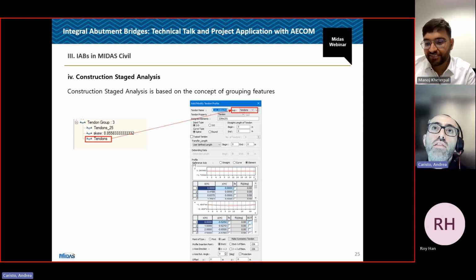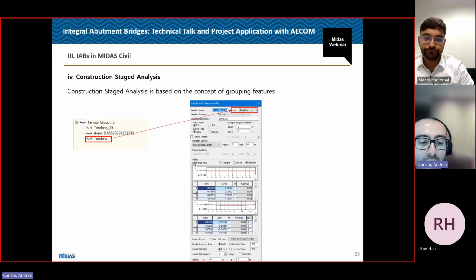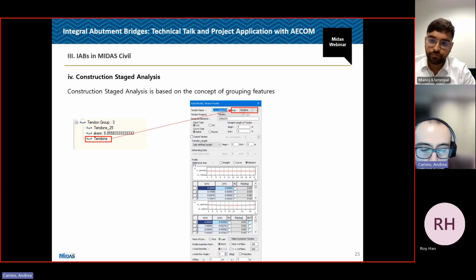So in this project, we have prefabricated beams, and we also have cast in situ deck with post-tension tendons. Now, the idea behind pre-stressed concrete, in very simplistic terms, is this: we all know that concrete is really good in compression, not so good in tension, and of course we have reinforcement taking care of the tensile part.